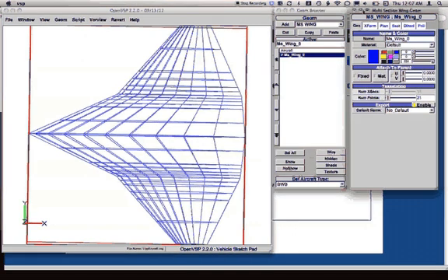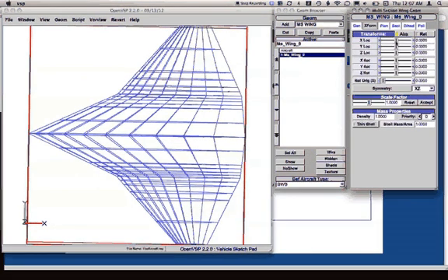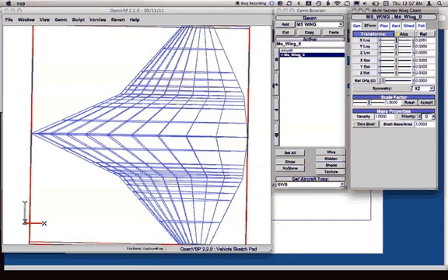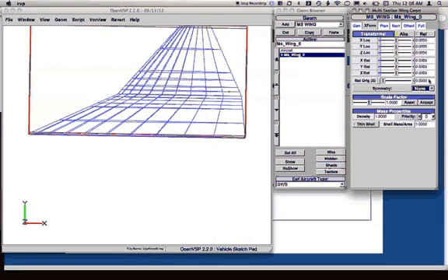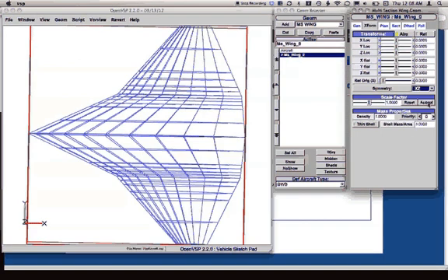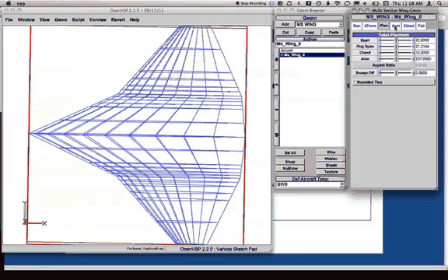And you'll notice it has various tabs as components of this. General tabs such as, I want to change the color, be able to change various other options here which we'll talk about later, we don't need to worry about yet. Things like location, so that way you can anchor this to a specific point in your geometry, as well as rotation. Symmetry, how the symmetry is actually defined, which is going to be important, for example, when you want to define something such as a tail section. So, I have a vertical stabilizer, so I don't need any symmetry, for example. Okay. I have the planform, and this is going to be one of the most important pieces here.